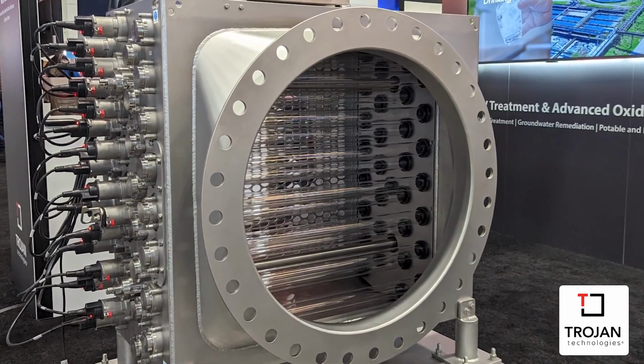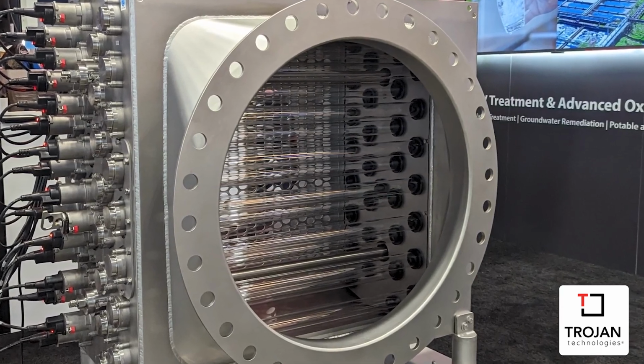For sure. And so what other types of products have you contributed to these installations? With UV AOP, what we would normally provide is a UV chamber. One of the chambers we provide most frequently now is what we refer to as the Trojan UV Flex AOP chamber. These systems are very easy to maintain. All maintenance can be done from one side of the UV chamber. That includes all standard maintenance, such as removing the lamps to replace lamp bulbs, removing sleeves to replace sleeves and wiper seals, and any calibration you may need for the UV sensor.